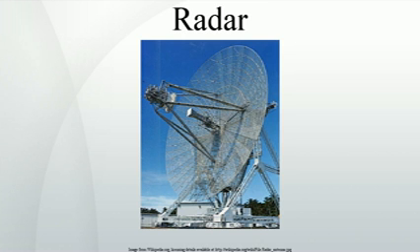Noise figure is a measure of the noise produced by a receiver compared to an ideal receiver, and this needs to be minimized. Shot noise is produced by electrons in transit across a discontinuity, which occurs in all detectors. Shot noise is the dominant source in most receivers.